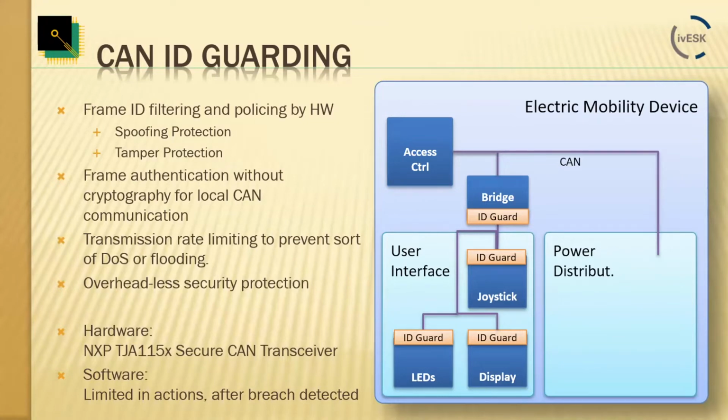For our purpose now, let's assume the regular 11-bit CAN identifier. These CAN IDs are assigned in your network uniquely. Of course there are always some exceptions in some protocol somewhere, but in regular operation, you would expect that each individual CAN ID is only used by one specific device.